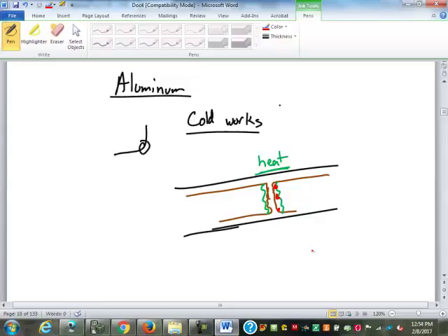They had actually taken the wires, and because you open the electrical box, pull the cover off the panel, and you look at the wires going into the breakers, and if they were gray, they were aluminum. If they were copper colored, they were copper. Well, one of the things they did is they'd take the wires, they'd go back a ways, cut them off, run copper into the box, and splice them to the aluminum, so they didn't have to rewire the whole house. I found one over by Cumberland that was done that way. It's dirty, but it's.